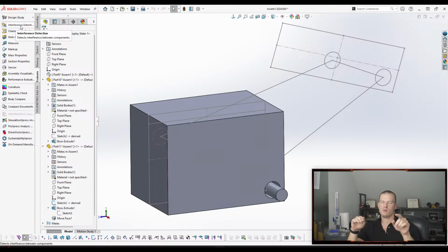And then I can go through my tree with interference detection turned on and prescribe those gaps and move those faces in as I go down to release a design, right? So that's a good check and good workflow that I found. Like, okay, maybe I want a press fit, or maybe I'm going from a slip fit to a press fit, and I don't want to have to change the sketch that's there. Or I want to try and keep my sketch lightweight or something like that.